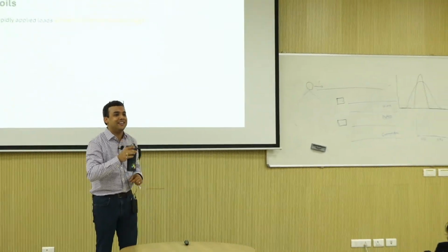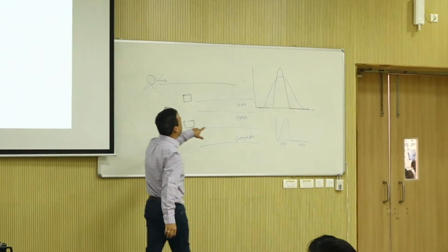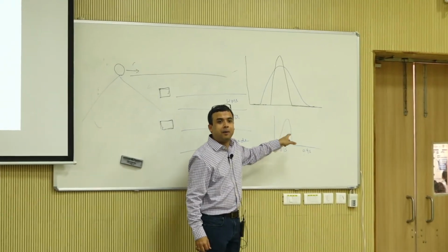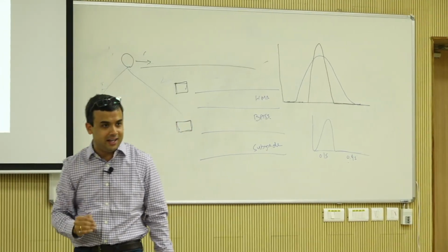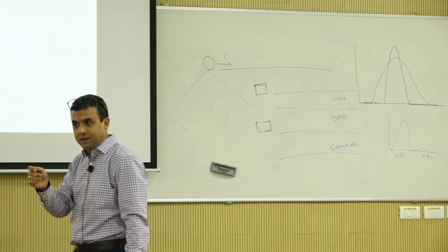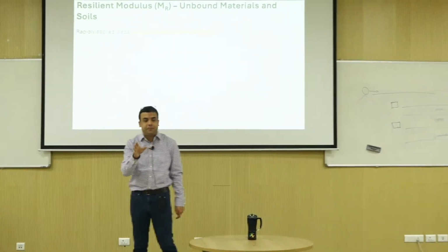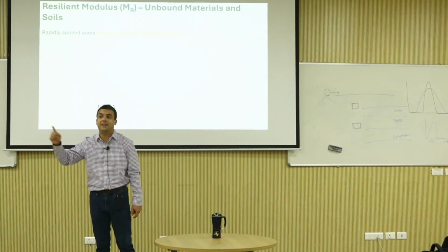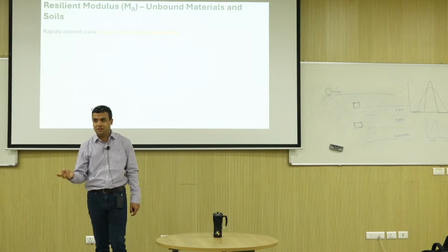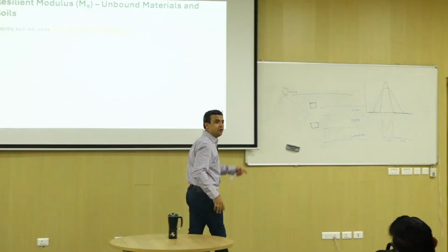So the point is, if you actually go and track the rest period and the pulse width, it should change depending on where you are in the layer. If you look at the code, for the subgrade, yes, it is acceptable to do it at 0.1, but it's actually also recommended to do 0.2 and 0.8 in AASHTO T307, whereas aggregates are usually 0.1 and 0.9.